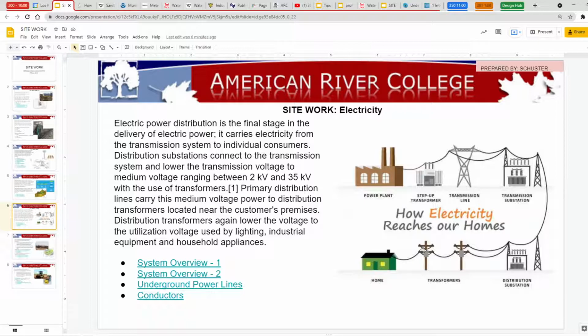It comes from the transformer on the power pole, and instead of having a wire drooping to the building, they usually drop it down the pole now and run that wire underground. Okay, so that's what's often done in Northern California and most of Southern California on new construction.